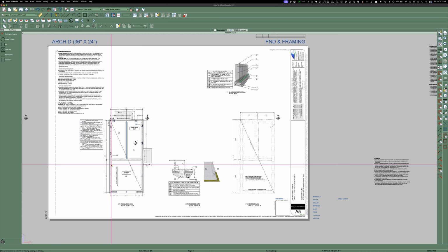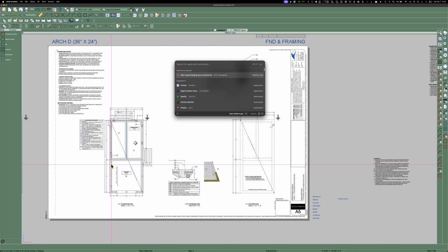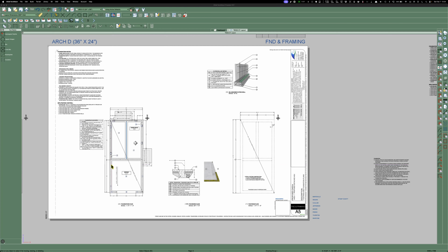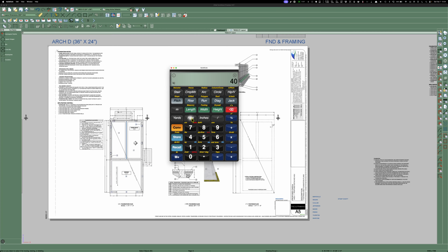So you could even check it right now. You could take a Construction Master. Hey, let's just do this. Let's go to Build Calc. And let's do 40 feet run, 18 feet rise, diagonal, 43, 10 and 3/8.